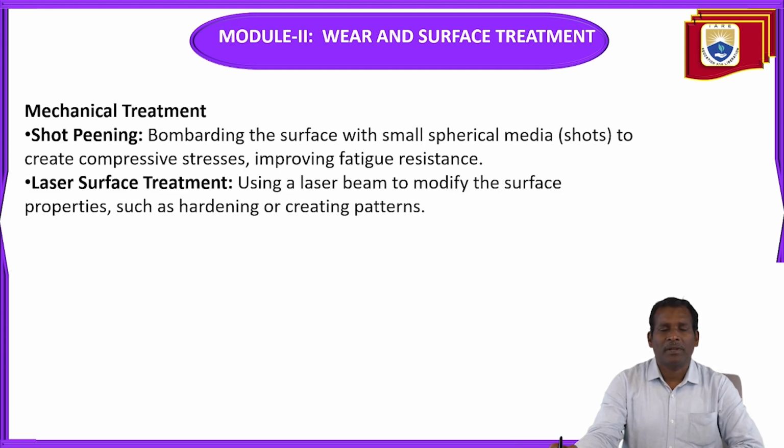The mechanical treatments are shot peening and laser surface treatment. Shot peening: bombarding the surface with small spherical media, that is shot, to create compressive stresses, improving fatigue resistance. So already you know what this fatigue resistance is; we have discussed it in previous sessions.